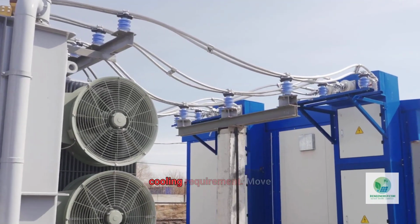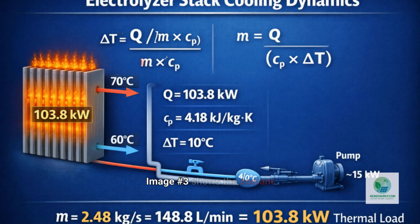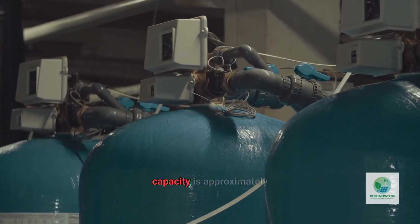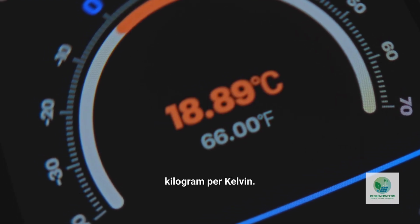Now let's quantify the cooling requirement. Move to image number 3. Image number 3 shows the coolant loop and the governing equation for temperature rise. The temperature increase of the coolant as it flows through the stack is equal to the heat load divided by the mass flow rate, multiplied by the specific heat capacity. For deionized water, the specific heat capacity is approximately 4.18 kilojoules per kilogram per Kelvin.